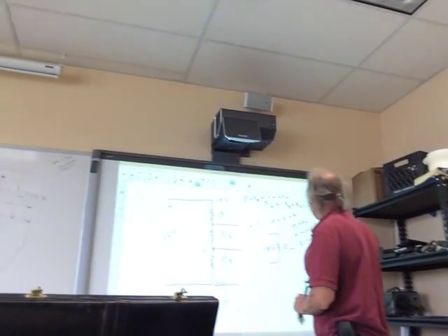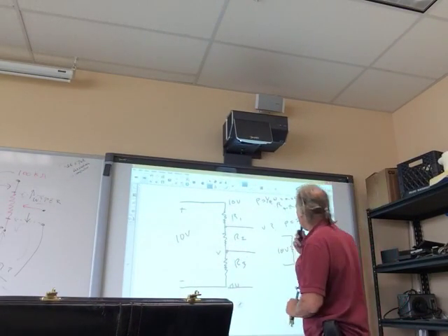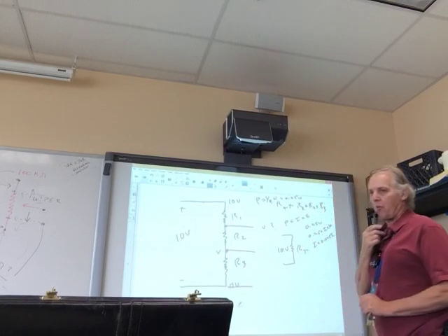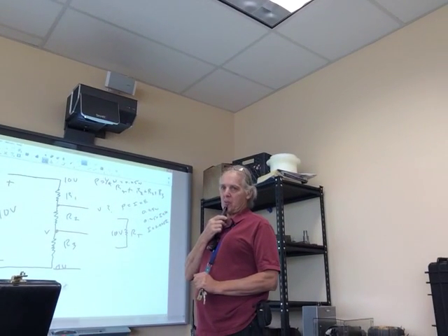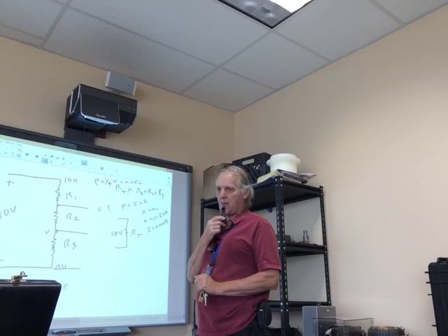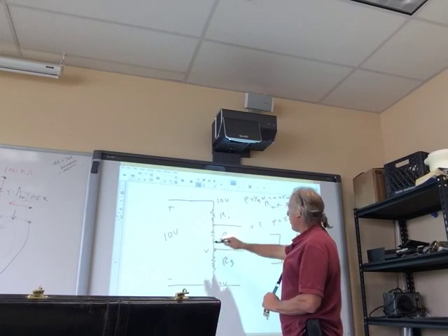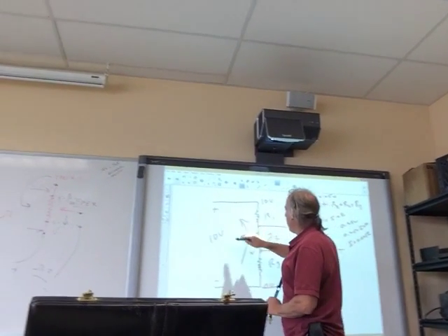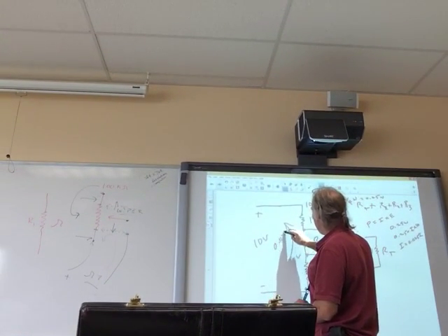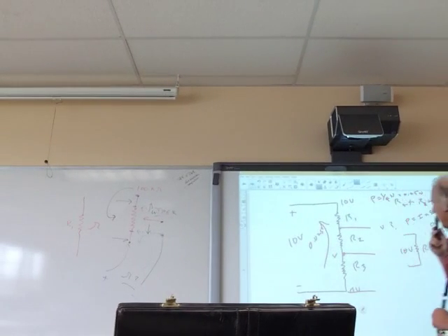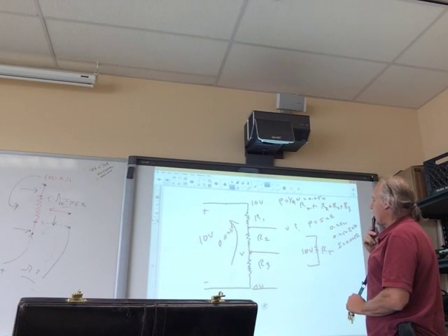So now I know the current through all three of these resistors. I also know the wattage. So now I know the voltage on all of those resistors and the resistance, don't I? How do I do it? Okay, so let's do it. Current through these resistors is 0.025. We know the voltage across all three.